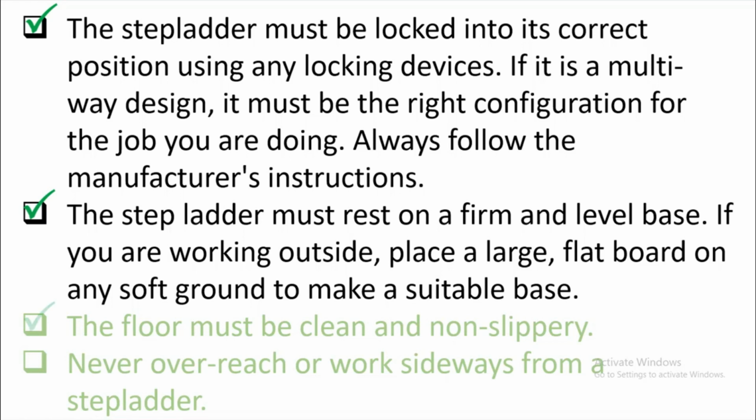Okay. The floor must be clean and non-slippery as discussed before on the straight ladder. If it is slippery, then your ladder may be unstable. And if you climb on it, it will collapse, it will trip, so you will fall from the ladder. So it's better to always clean the area before you start.